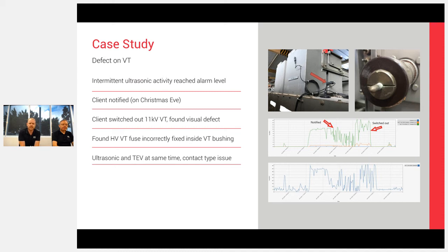So here's another case study. So this is a defect at a VT. This is a rackable VT on an 11 kV switchboard. This one occurred on Christmas Eve. So we found the PD activity via the monitor on Christmas Eve. Within 2 hours, we'd notified the customer, and within another 2 hours, they had people down there and they'd